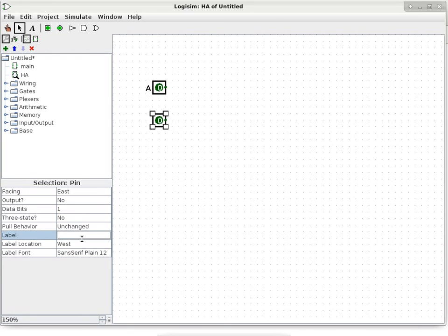Okay, here we go. And how many output pins do we have coming out of a half adder? There's the result and there's the carry. Okay, 2 outputs. So now we'll go ahead and pick up two of these. Okay, so that's 1. Label this one as our result. And we'll pick up another one and label this one as our carry. Okay. How do we connect these things?